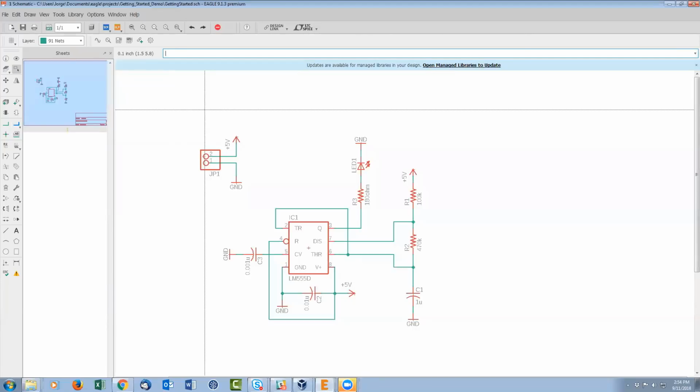Now, if you've shared the schematic or the board with somebody else, let's say you emailed the board and the schematic, all of the information required for this board and schematic to work are there, but they won't really be able to back reference to the library because they don't have the original libraries. Yeah, in those situations, they'll have to extract the libraries from the design itself, make whatever changes, and then update the design based on that. And we'll go ahead and do that as a demonstration on another webinar as well.